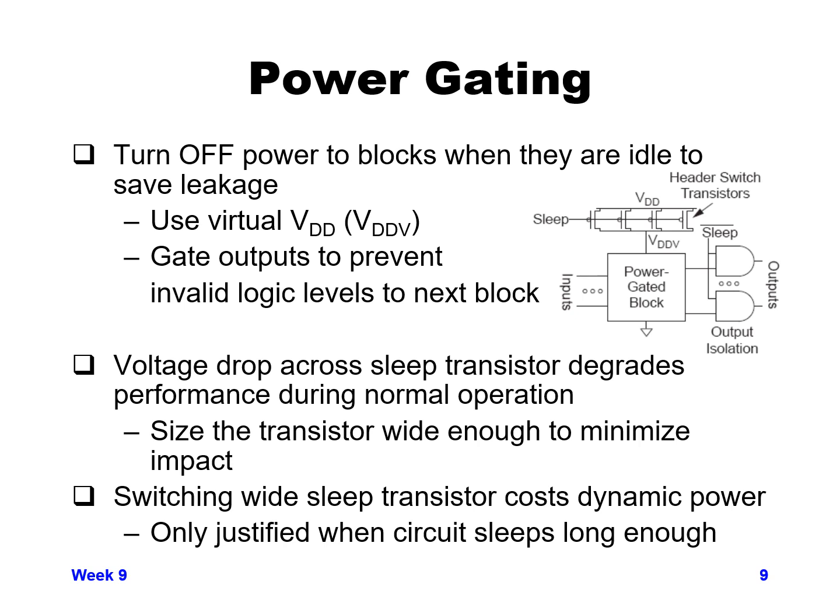And in the circuit that's shown on the right there, if you have a sleep value that's controlling those transistors, when you're not in sleep, sleep is 0, and so it turns those transistors fully on. You allow VDD to go through those PMOS transistors and power up that power gated block. And so when you're using that block, you have all of those transistors on, and you provide something that's really close to VDD to that entire block of logic.